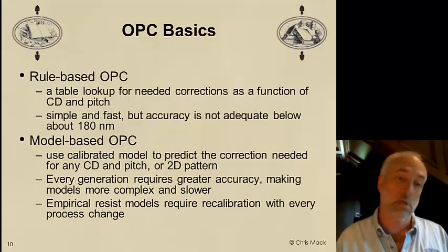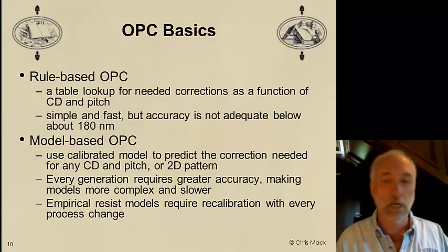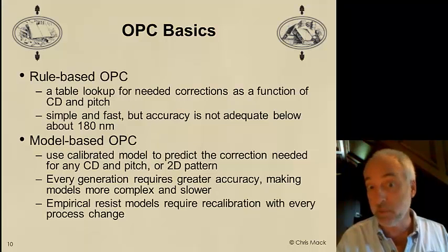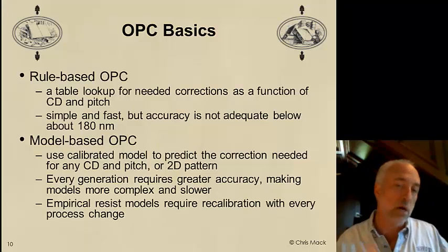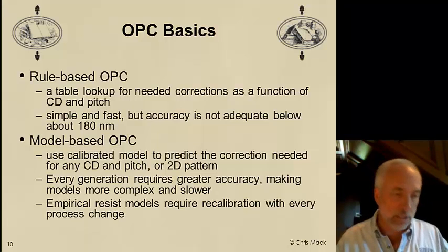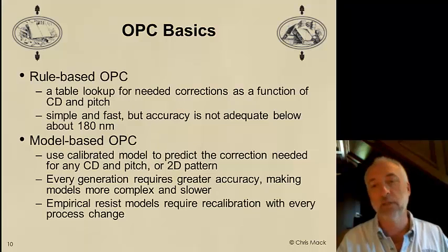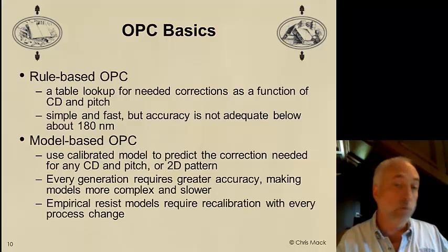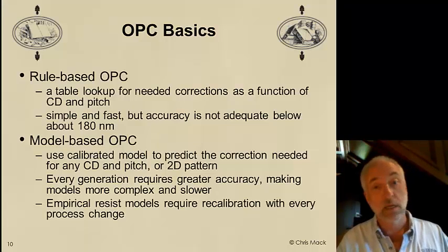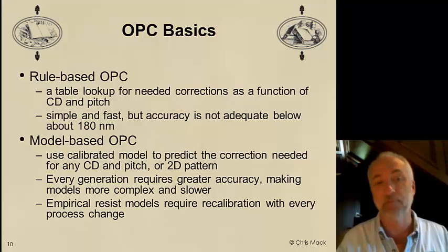And the result is great difficulty from a computation perspective. Today, model-based OPC runs to calculate the correct mask pattern we need require calculations on hundreds of CPUs, hundreds of computers running in parallel for multiple days in order to make a correction of one mask.